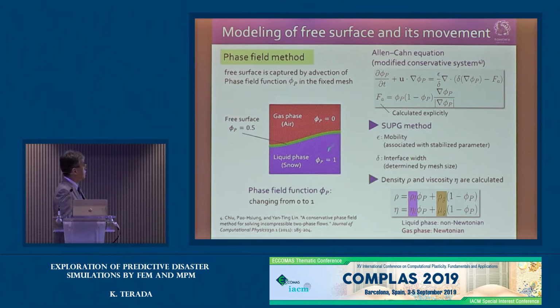By using the nodal value of this phase field function, we can calculate the density and the viscosity by this equation. Here, the liquid phase is assumed to be non-Newtonian, but the gas phase is assumed to be Newtonian in this case.